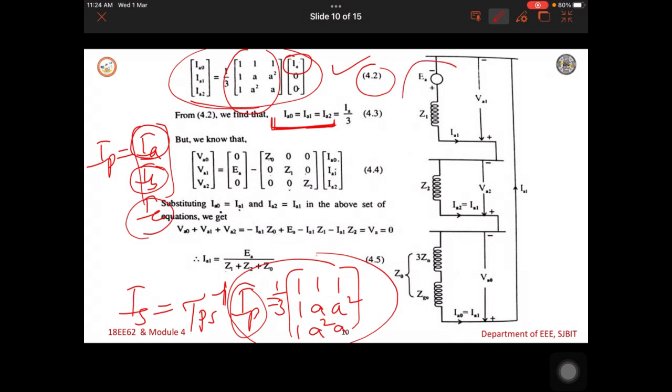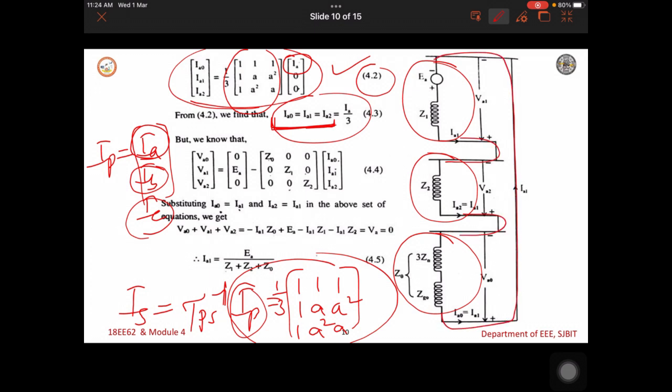That means, the positive sequence network, negative sequence network and the zero sequence network, these three networks are connected in series. Why? Because it is clearly said that the sequence currents are equal. So, if you connect them in series, here it is shown as series connection. All the three sequence networks are connected in series. Therefore, IA1, see here IA1 and this is IA2 and this is IA0. So, IA0 is flowing as IA1, IA1 is flowing as IA2 here. Therefore, all the sequence currents are equal.